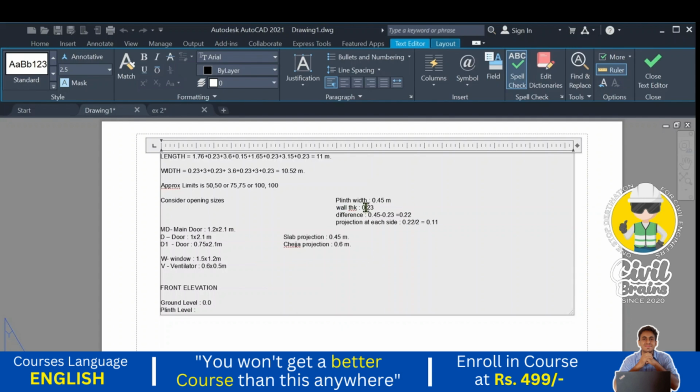Plinth width 0.45, and what is the height of the plinth? As per standard practice, we can consider the plinth height as 0.45 meter. Width also 0.45, and height also 0.45.